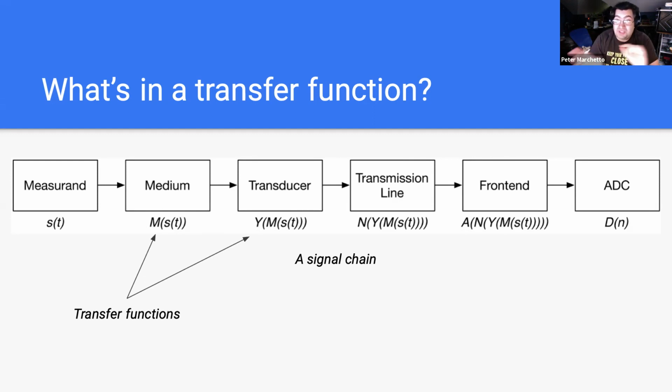And now we change completely the way that we're looking at the signal. Up to this point, everything has been continuous over time as a continuous variable. Now we're in the discrete space, and we're moving from being a continuous time curve to instead being discrete time measurements, where we actually take a particular value at a particular moment.